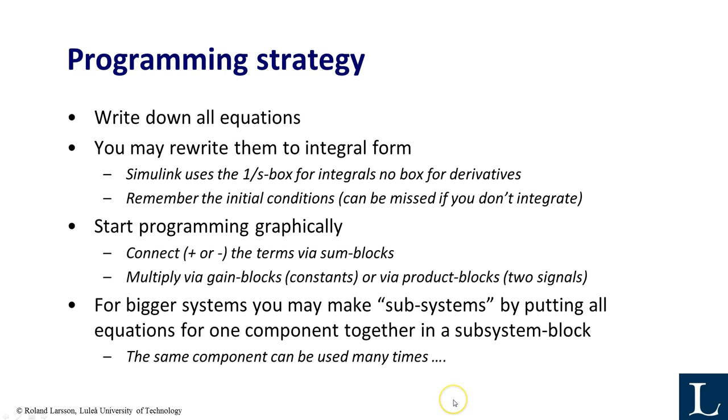If you have a bigger system, you may form subsystems and make ready-made blocks. If you have a hydraulic cylinder, for example, you may make a ready-made block for it, and then you don't need to make a new one all the time. Or if you have some standard components, you may store them as subsystem blocks, so you can use the same component many times.